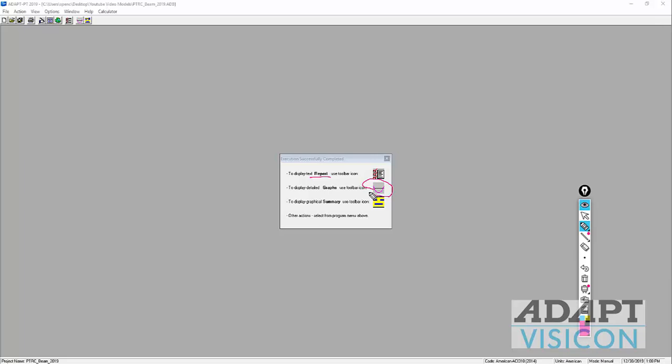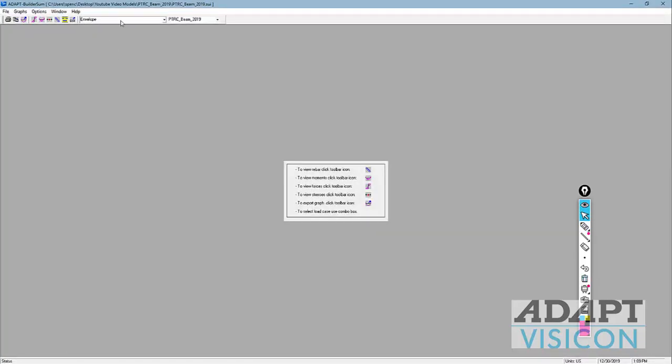This is really on a load case basis, an envelope of load combos, and then we can also look at a summary. This is both graphical and tabular. So we're going to use the summary first. If we go to the summary, this allows us to check different combinations. Min and max would indicate that skipping is active. So we have a maximum and minimum range of results for the live load that was placed in the different skip patterns. And then we could also check the envelope.